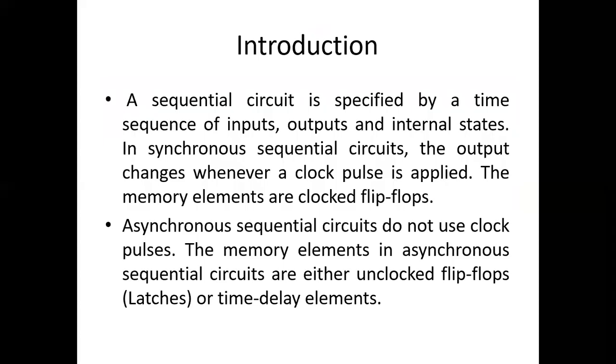First, a sequential circuit is specified by the time sequence of inputs, outputs, and internal states. In a synchronous sequential circuit, the output changes whenever a clock pulse is applied. The memory elements are clocked flip-flops. Asynchronous sequential circuits do not use clock pulses. The memory elements in asynchronous sequential circuits are either unclocked flip-flops or time delay elements.